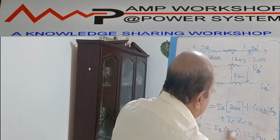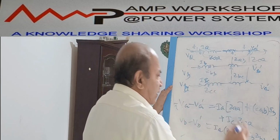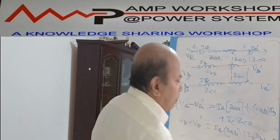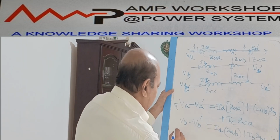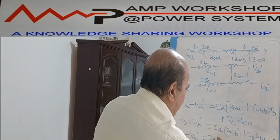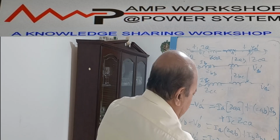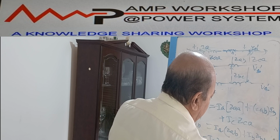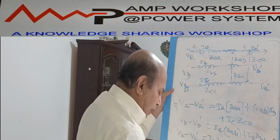That is IC, the C phase current, and the mutual induction between these two, B phase and C phase, that is ZCB or ZBC, you can say. There will be a voltage drop. So this will be the voltage drop equation for the B phase. Similarly, VC minus VC dash is equal to IA times ZAC, because A to C phase, plus IB times ZBC plus IC times ZCC. This is what we are getting.